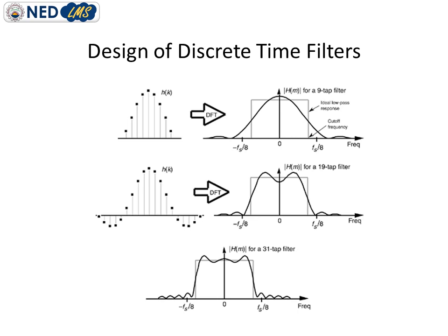So here you can see as I am increasing the filter coefficients, as filter coefficients and convolution are very much related, as I can extract the filter coefficients from the impulse response. So this impulse response is actually utilized to extract the filter coefficients, and from these coefficients I design the difference equation, and with the help of that difference equation I actually design my FIR filter.